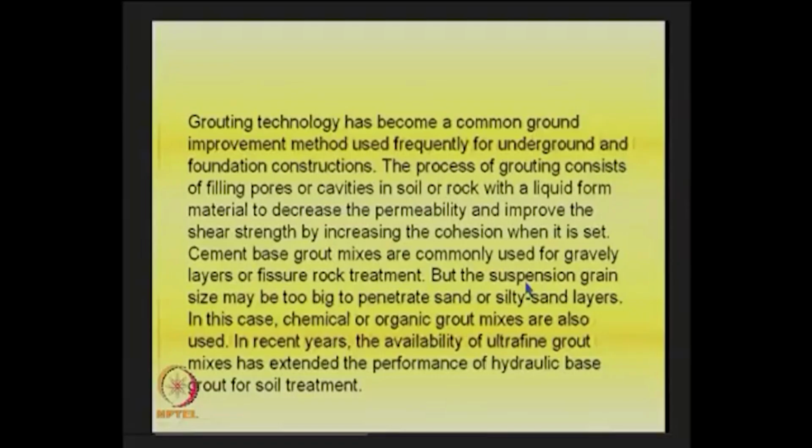It has to occupy all the voids, and in some cases when the grain size distribution of the soil itself is very low, the suspension may not get into the system, and what we do is that we try to go for chemical or organic grout mixes, which is quite useful in those conditions.